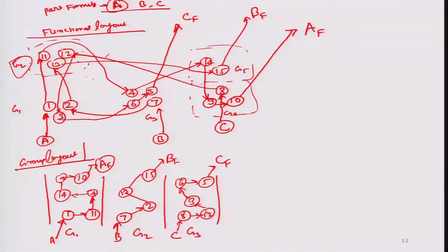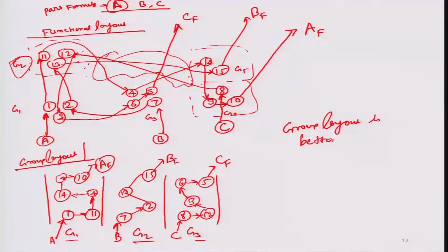So you can see that the number of groups is lesser as compared to the functional layout, and these complicated pathways are completely or partially eliminated in the group layout. That's why group layout is better than functional layout.